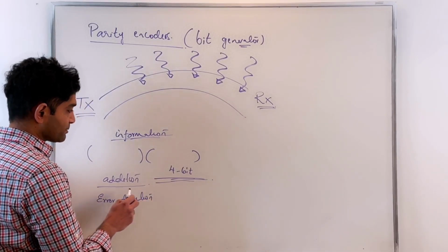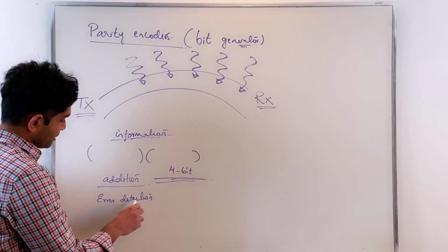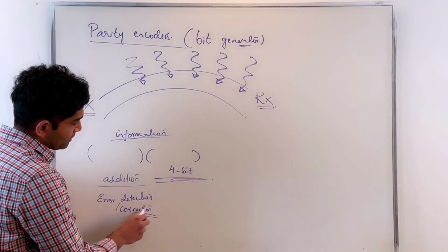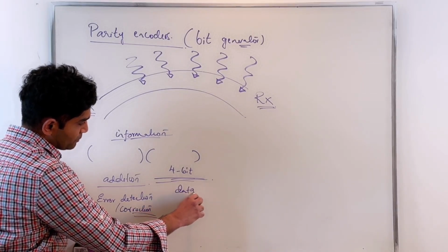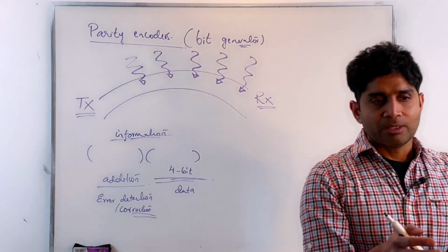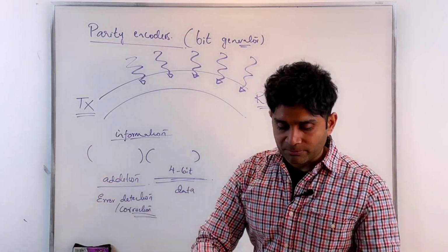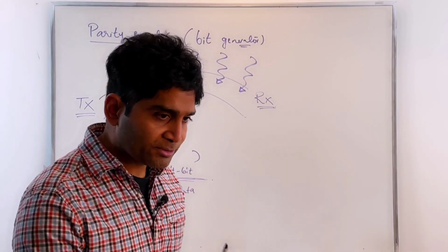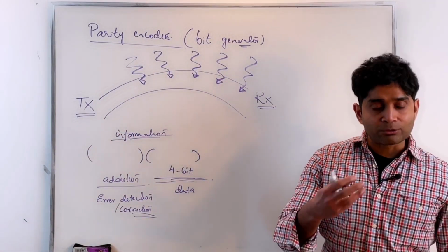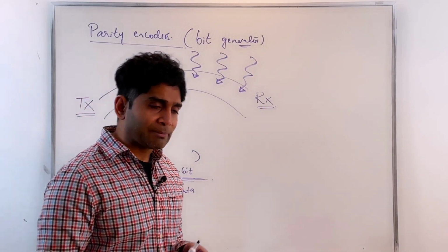So these are codes that are tagged along with my information, error detection and correction bits. My data, this is my data. So your data packet now consists of your actual data and also these additional bits that perform the role of detecting the errors due to noise acting on my signal, as well as correcting those errors. And there are multiple different algorithms that can be implemented on this.